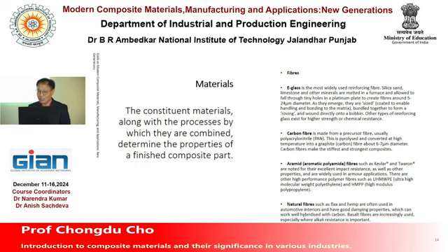At that size, the E-glass strength is more than 1 gigapascal. That means it greatly increases if you make it in a small dimension, because in a small dimension, large defects cannot be included.